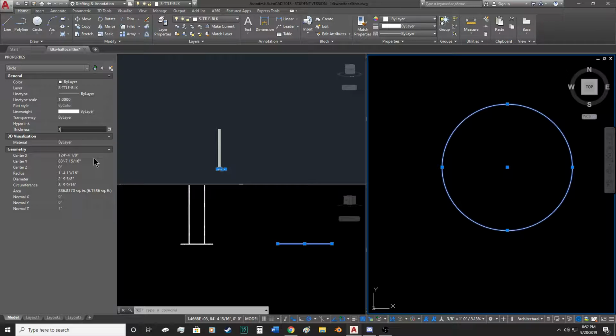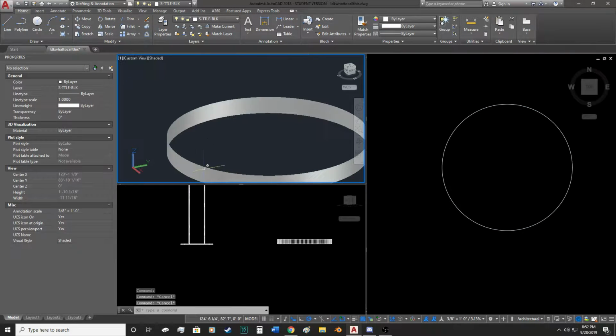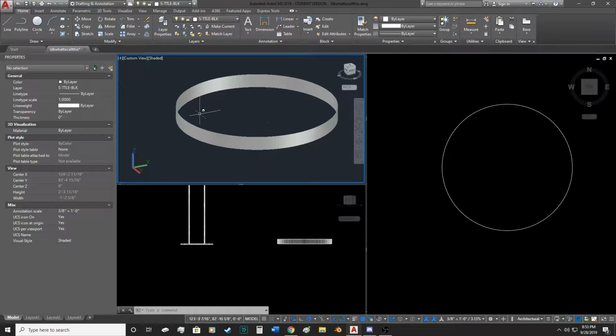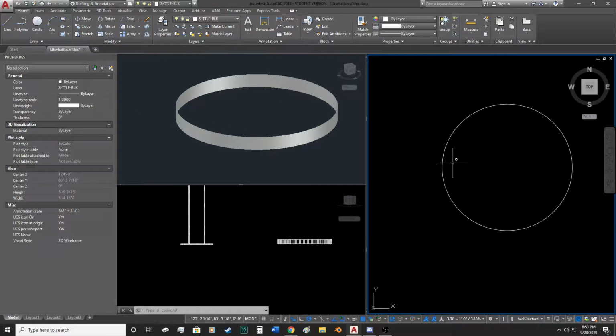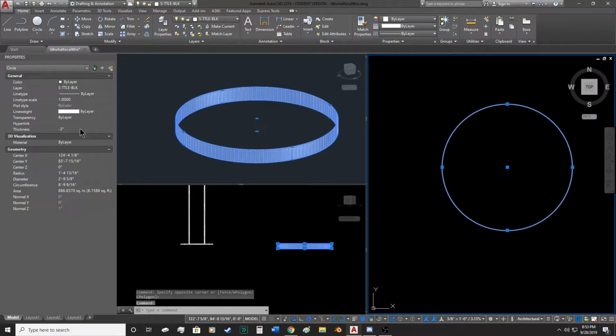And you might be thinking that it's the same thing as the extrude command, but it's really not. You can see right here that it only makes the outside of the polygon solid. It doesn't do anything with the inside of it. There's all this air, and it's not solid. That's what thickness does. You can input -3 inches, and it'll actually go down below the x-axis.